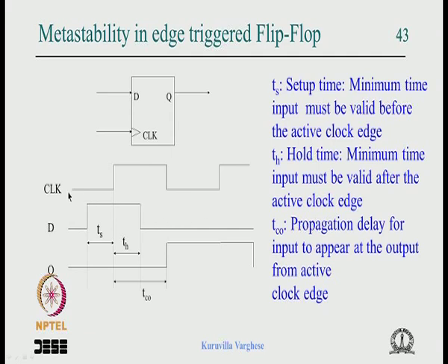During the negative clock period the master is in the transparent mode. When it goes positive the master is cut off, and whatever is captured in the master is transferred to the slave and you get the output. So there is no edge trigger magic, as if something happens during the edge. Nothing happens during the edge in digital, that either it is 1 or 0.